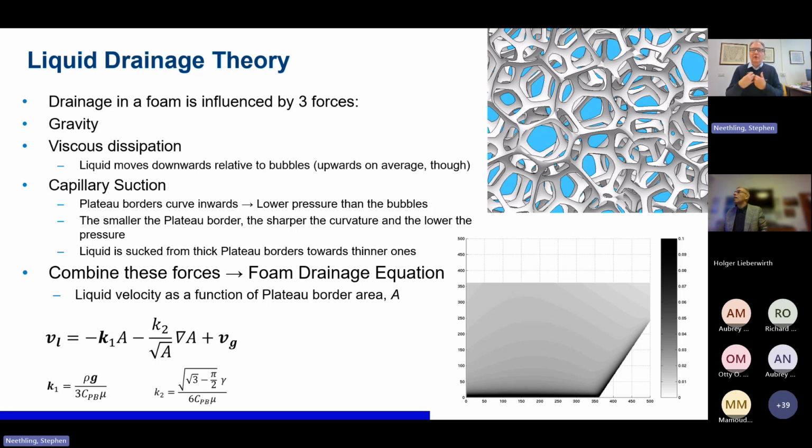So particles fall off the bubbles in the froth, but if you think about it, the water motion in a froth has to on average be upwards, and so particles, even if they fall off the bubbles, are not necessarily falling out of the froth overall.